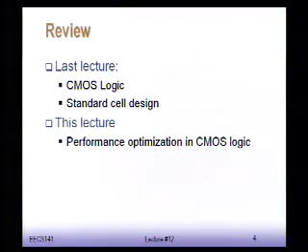All right, so let's recap last week and what we've done. So we started looking at complex gates in CMOS and how you do design in standard cell. Standard cell design really means you have a subset of logic functions that have been pre-implemented for you by the foundry. And not only do you have a subset of logic functions, but also a subset of sizes for each of these logic functions.